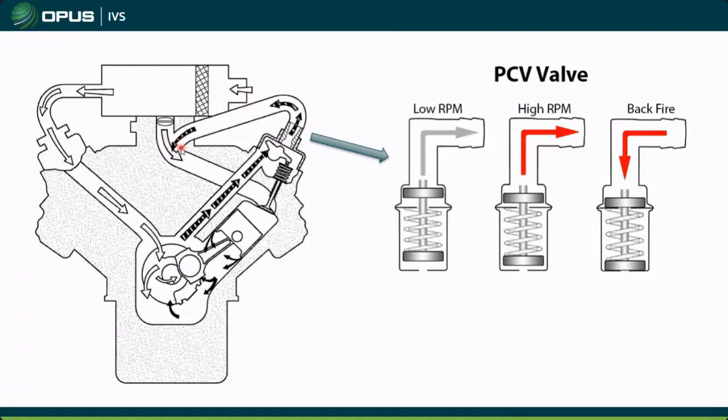This was basically an early emissions control device, and it worked on a very simple setup: this PCV valve would open and close at certain engine RPMs, certain load and vacuum characteristics of the engine, in order to recirculate those blow-by gases and crankcase gases efficiently without really having an effect on drivability. So for the most part, a very simple system and, honestly, pretty effective.